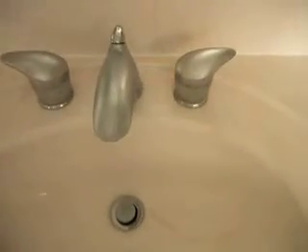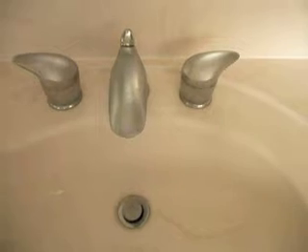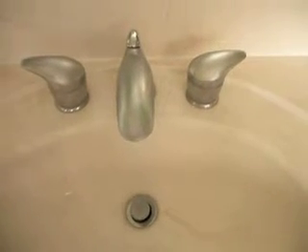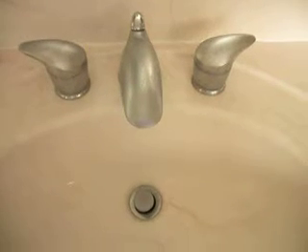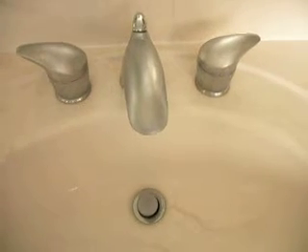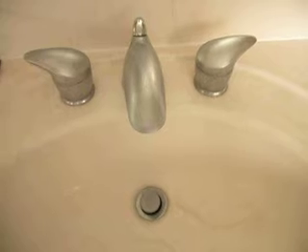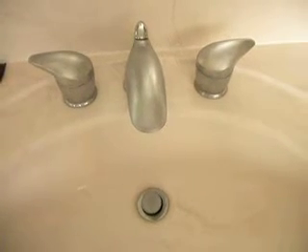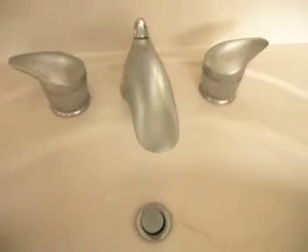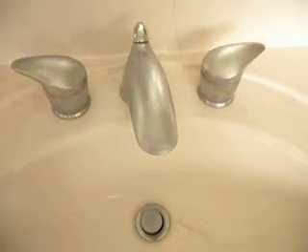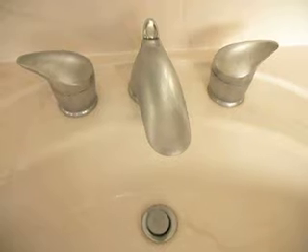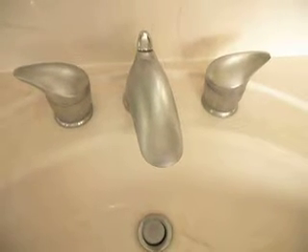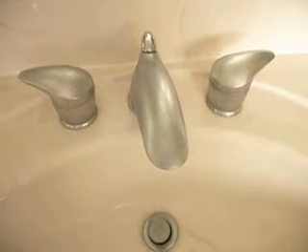Now we're here today to look into the water system of the house. A few months ago I became aware that there was an AC voltage on my water system at my house that appears to be originating at the utility neutral connection. I'm going to show you that voltage in a couple of different ways. The first way is with the water system connected to the utility system grounding connection, which is also the neutral connection. And then I'm going to disconnect from the utility system.